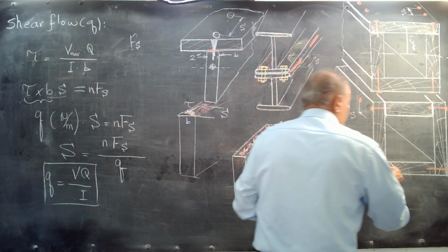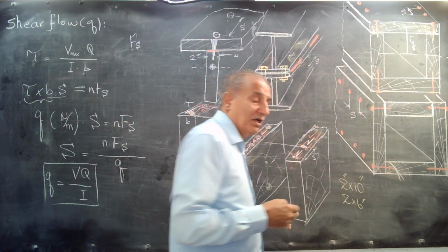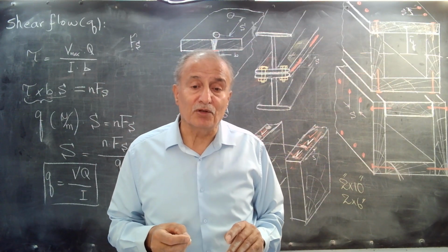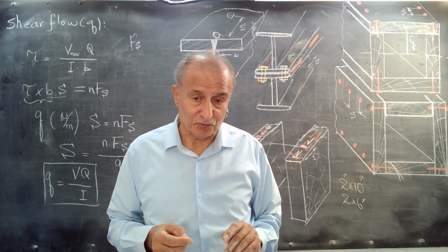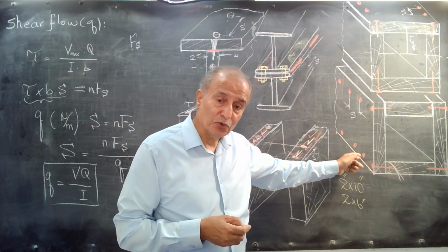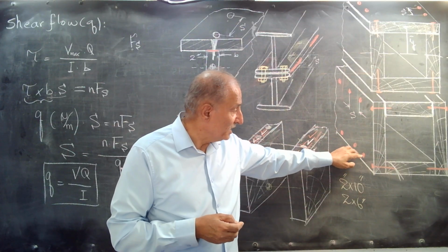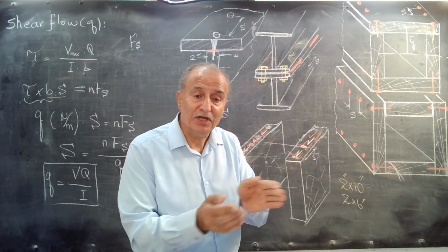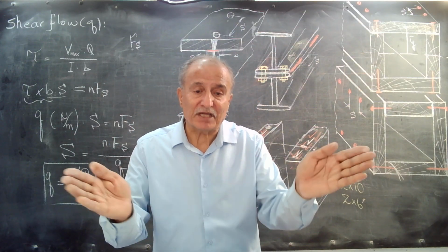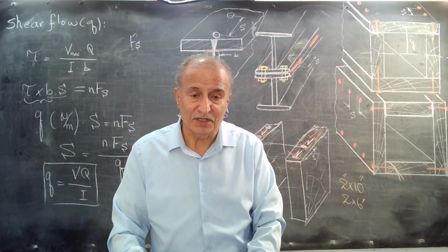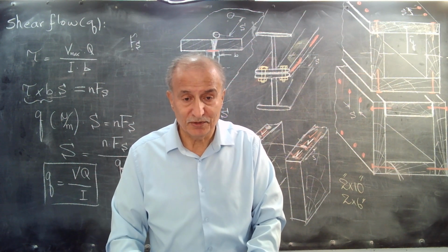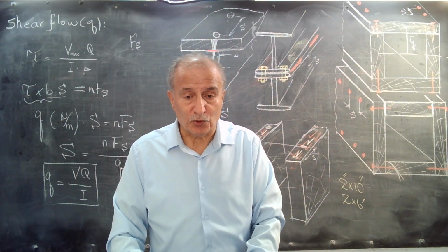The longitudinal one, along the grain or along the fibers, gives us the maximum modulus of elasticity for the wood. But what happens? If you use nails, a screw or bolt, or any holes that you make in the wood, they separate the fibers of the wood from each other. And if these nails are very close together, cracks happen and the wood splits, especially where the beam has maximum shear, at the supports. This is one of the modes of failure of joists.